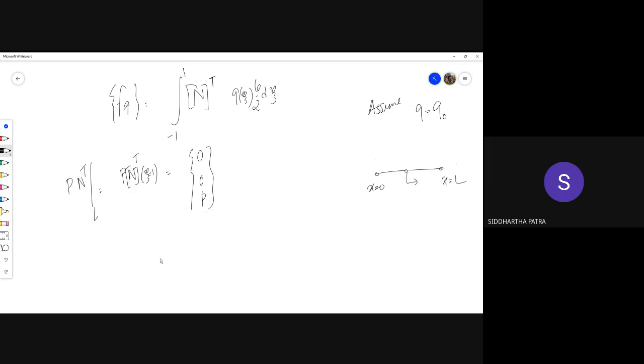Okay, so in the end your expression should be V hat transpose multiplying the element stiffness matrix that you found out, which is the total stiffness matrix now, because you have spanned the entire geometry with a single element, multiplying your u hat. Remember u1 is 0, and that's why v1 is 0, but this one is true for all v2 and v3.